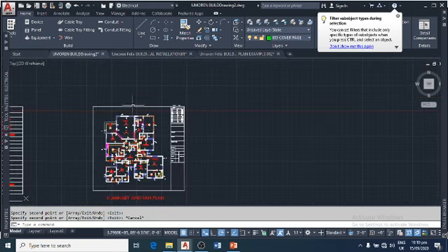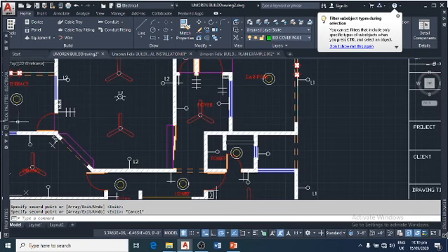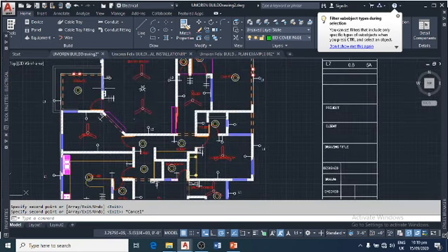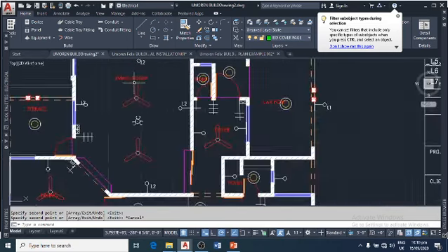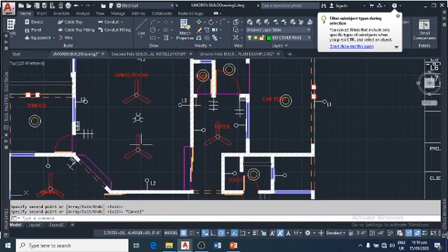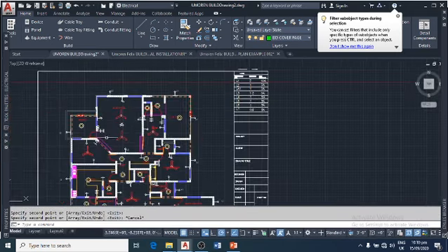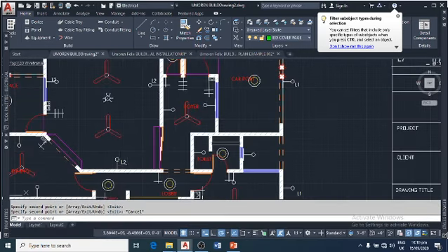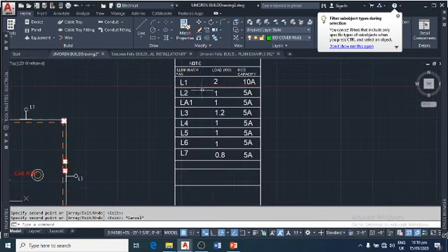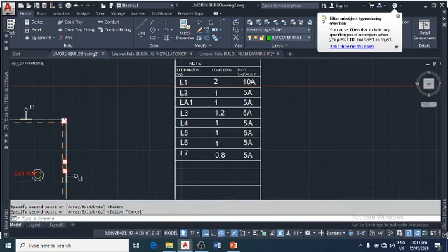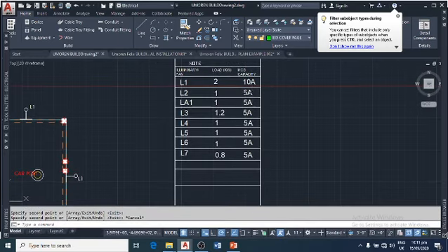Okay, going back there, we also group the subcircuit for every other thing we have there. So we start with L2, the living room. For L2 we are grouping the lightings, fan, and the terrace here. So after grouping L2, the maximum load is 1 kilowatt and the MCB rating is 5 ampere.